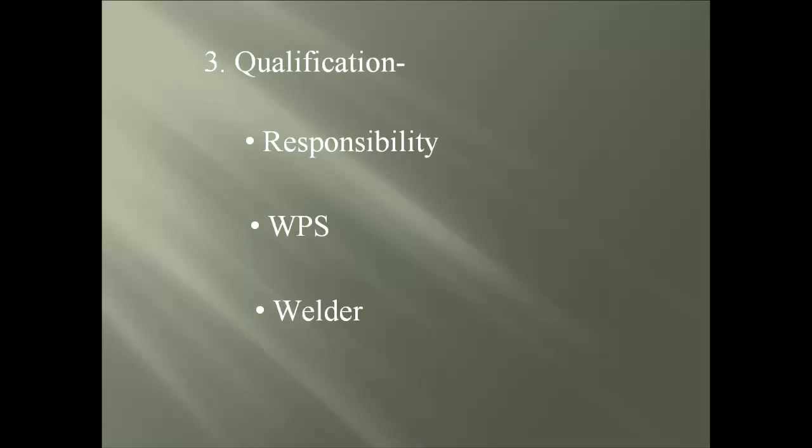Once a welder is qualified, they are considered to be effective indefinitely unless there is a lack of use for more than 6 months or there is a reason for questioning the welder's ability during production welding. And as alluded earlier, these records shall be available by the contractor and examined for compliance at any time.